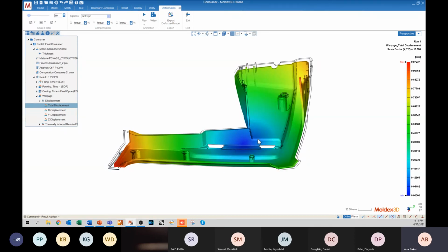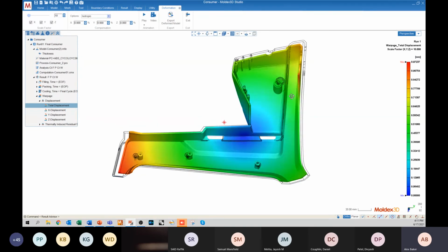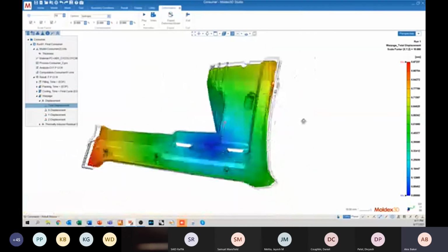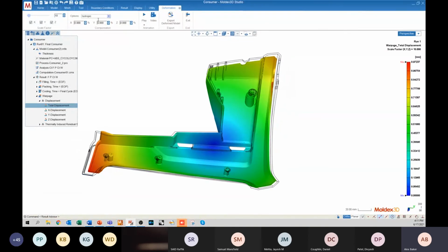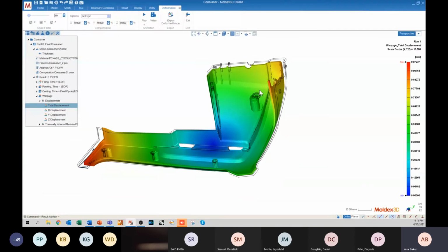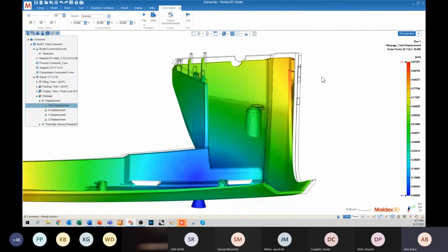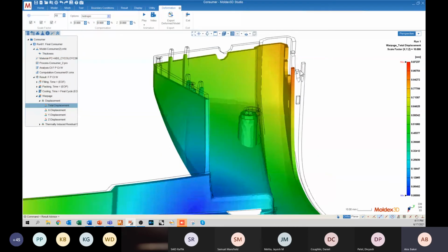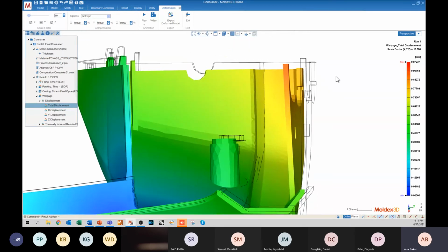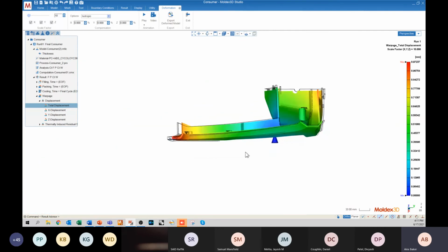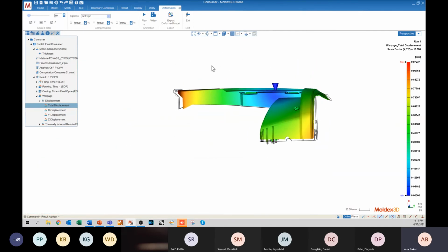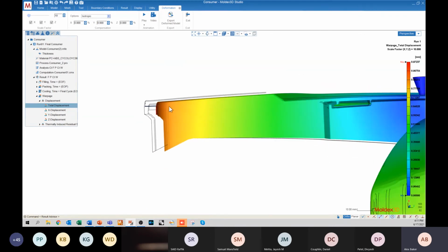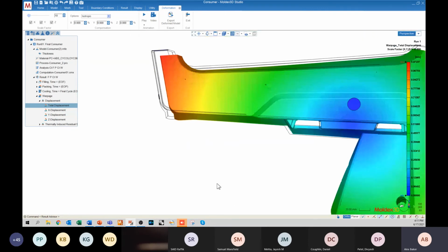The amount you scale is really dependent on how much warpage you actually have with respect to the size of your part, which might depend on the material type that you're using or the structural rigidity of your part geometry. But scaling allows you to really visualize the warpage a little bit better. So for example, we can see that this feature here is very obviously warping inwards, right? This surface is really kind of warping inwards. Whereas something like this on the same magnitude really isn't going anywhere. Maybe a little bit downwards, but it's mostly just going inwards. It's not really going laterally at all.